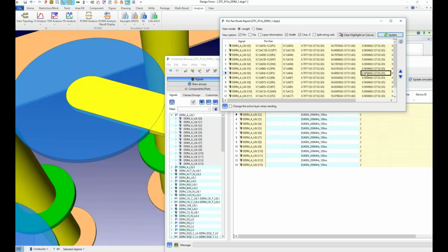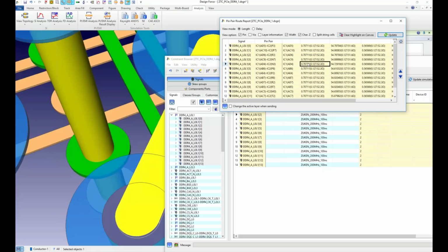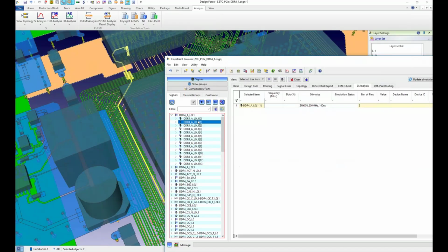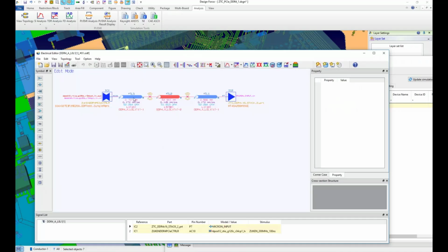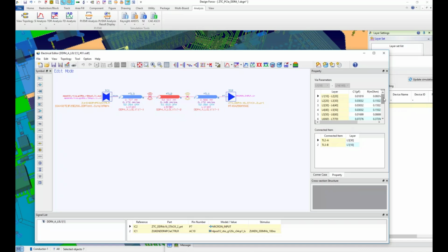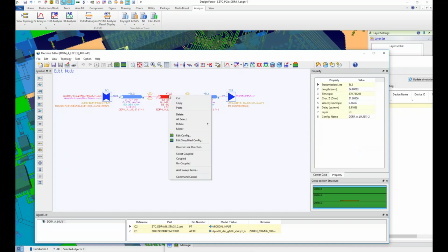This allows to do a review of the board routing structure and to figure out where do I have violations against my impedance rules. You get these impedances as well in a more depicted manner if you create this electrical equivalent circuit. So we've selected one of the tracks, and then I have here this equivalent circuit with the transmission lines with impedance figure. So this is a microstrip, the fan out. Then we have the wire here. That's then the automatically created wire model with the parasitics, the capacitance, resistance, inductance. This is then the strip line on the inner layer.